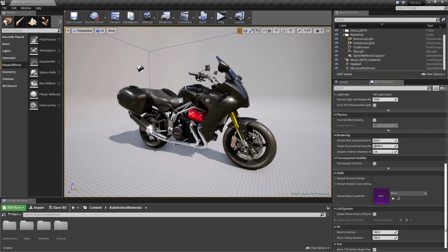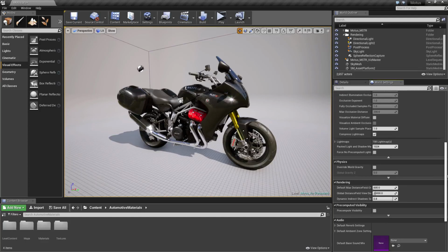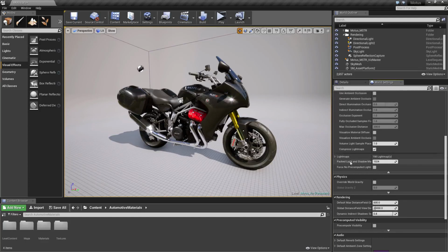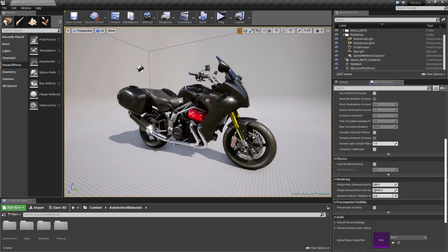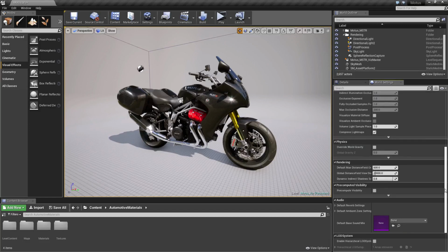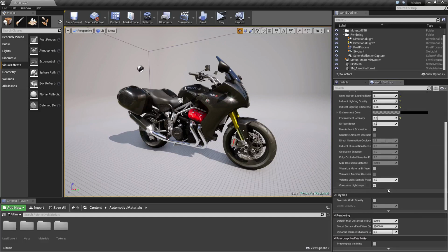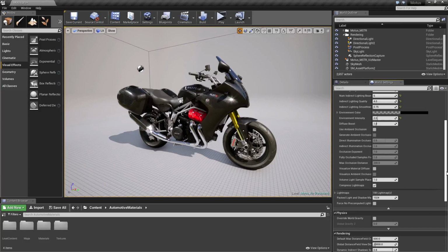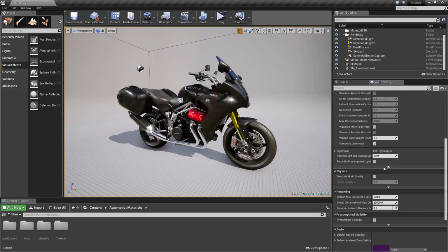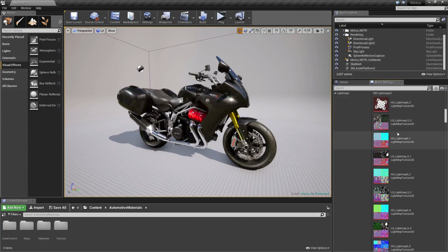Let's take a look at what happens with lights when they're baked out in Unreal and what we do with those lights or those images that are baked out. This is where we create something that is referred to as light maps. Light maps can be found through the world settings. If we go underneath our lighting setting and expand our menu out, we'll see light maps, and we can see that in this scene I have 198 light maps that I'm working with. For the final sequencer, I rendered or baked the lighting out at a high level, and you can see all of these different light maps. They look very strange, with some strange coloring going on.